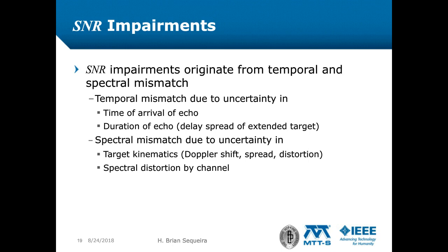Also, for an extended target, the leading edge of the target arrives at the receiver earlier than the trailing edge, with times of arrival everywhere in between for those portions of the target that are within these time boundaries. These temporal profiles, in turn, depend on the look aspect of the target. Because the target and its look aspect are unknown a priori, sampling of the signal must necessarily extend beyond the echo's termination. As a result, noise energy is sampled for a somewhat longer duration than echo energy.